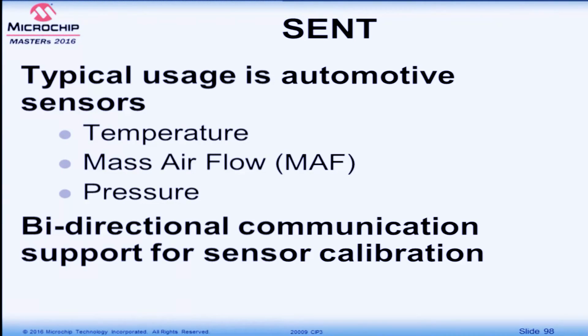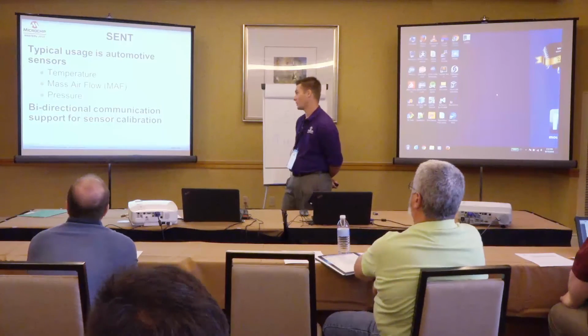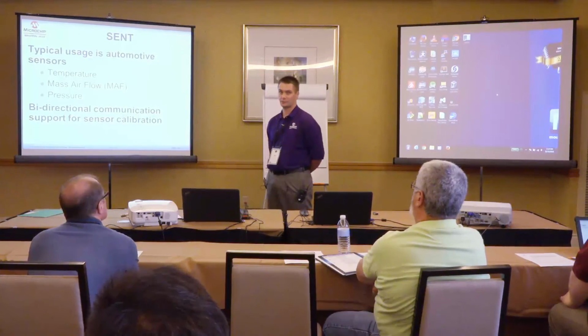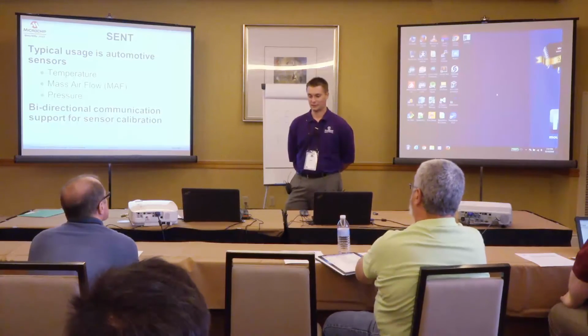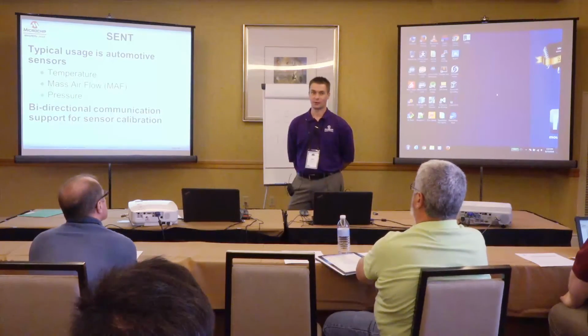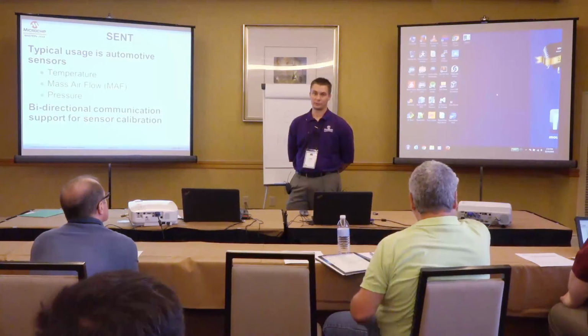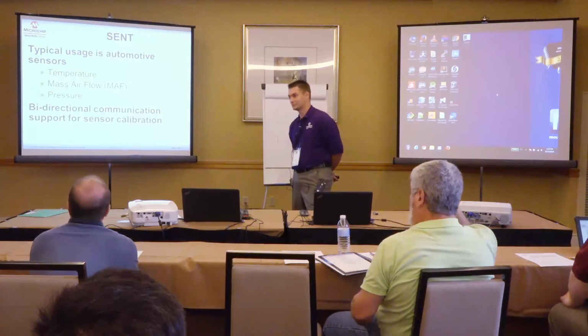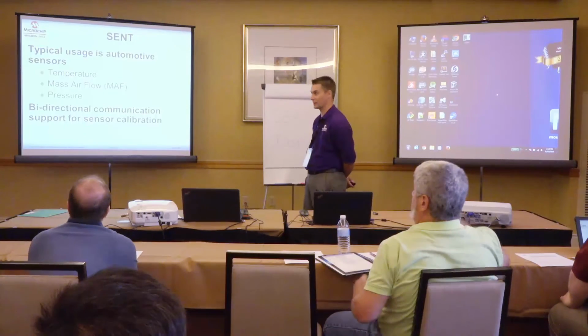So a typical usage of this is going to be an automotive sensor. It's kind of what it was developed for, although you could use it for anything. That might be temperature or pressure. And there was an extension made to the specification to allow bidirectional communication in case you wanted to calibrate a sensor or query it or anything like that in your system, self-test.